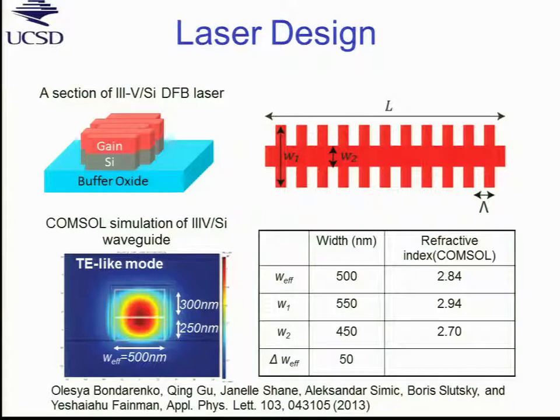And of course, beforehand, we remove the substrate, the carrier of the gain media. Then we define the structure, and when we calculate the modes, you can clearly see that it's about 50-50. So the mode gain overlap is about 50%. Compared to evanescent coupling with other approaches, it is less than around 4%. So that's a significant increase in the gain mode overlap, which is very critical for efficient sources.